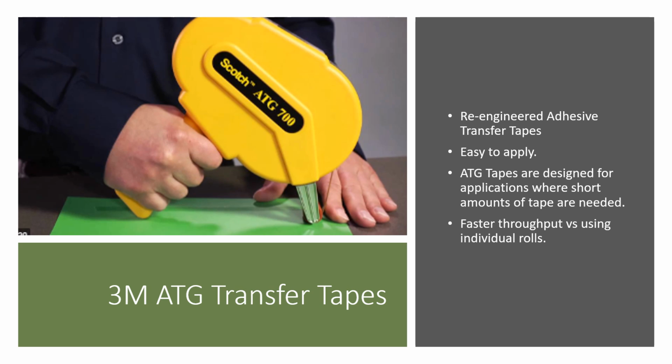To help improve customers' throughput when using their transfer tapes, 3M developed the ATG series. The ATG series has several tapes that work on multiple surfaces. To use the ATG gun, you put the roll of tape in it. You then put the applicator to the substrates that you're going to use. You pull in the trigger and then you slide the applicator until you're done applying the tape, release the trigger, and then you can move on to the next substrate.